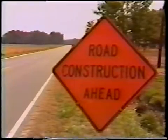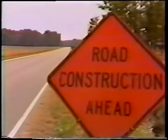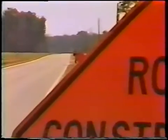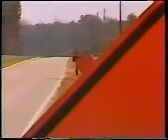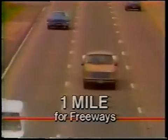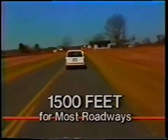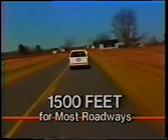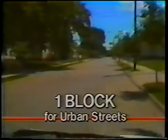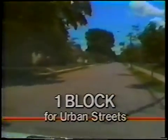The advance warning area, from the first sign to the start of the transition area, should be long enough to give the motorist enough time to respond to the control devices. For most operations, the length can be 1 mile for freeways or expressways, 1,500 feet for most other roadways or open highway conditions, or 1 block or more for urban streets.